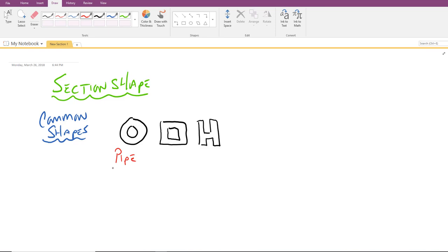There's no right or wrong way for this particular shape to be drawn. For some reason we tend to draw them as H shapes when we indicate columns and I's when we indicate beams. But the major difference when we're talking about wide flange shapes, or the W shapes, is that beams tend to be tall and fairly narrow in the flange area. Tall in the web, narrow in the flange. And with W shapes for columns, they tend to be square or nearly square.